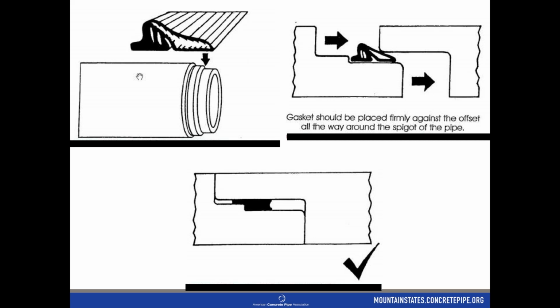I don't want to say roll, but it folds over. And those teeth in that lubrication chamber catch and lock into place and hold it into place so that you can seal it. We had someone one time take some lubrication from a job where they had a profile gasket and use it on a self-lubricating gasket, and these gaskets were sliding off. The problem was it caused it to slide off, and as they were homing and trying to get this pipe put into place, it was slipping and sliding in, and we actually had gaskets that were hanging inside the pipes.